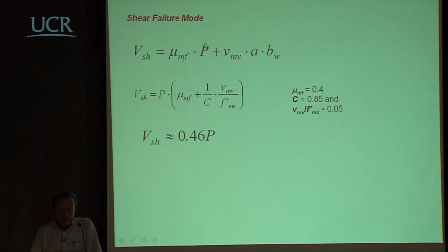Now, if you play with numbers and you take out the vertical load and then put the vertical load, of course, down here, you see that you can make some simplification, considering that the vertical load divided by these two will be the compression strength multiplied by a factor which is again depending on the vertical capacity of the wall.